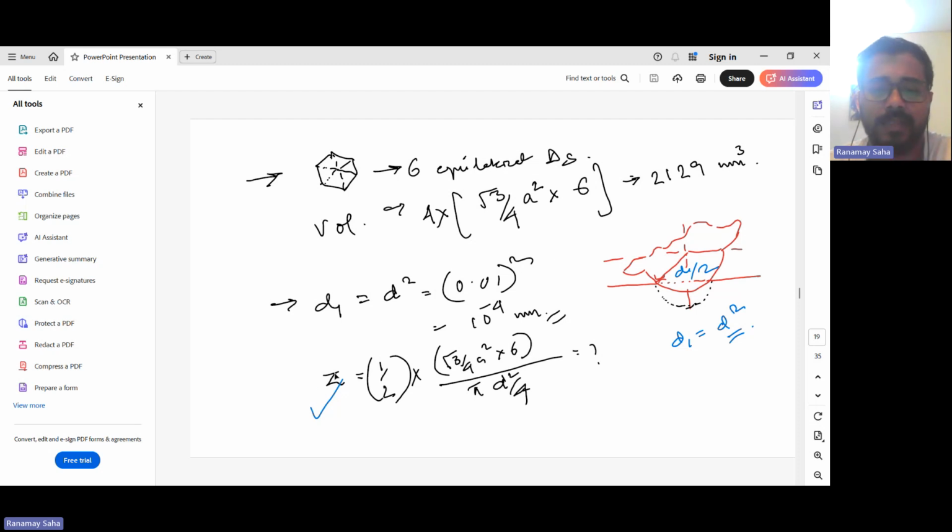Right? And then the number of particles can be found out by three factors. First is the concentration of the particles in the solution, multiplied by the area of the particular hole which is to be inscribed, and divided by the area of one grit. Considering this to be a sphere, we can find the number of particles. So we have found the diameter, the volume of the hole to be inscribed, and also the number of particles.